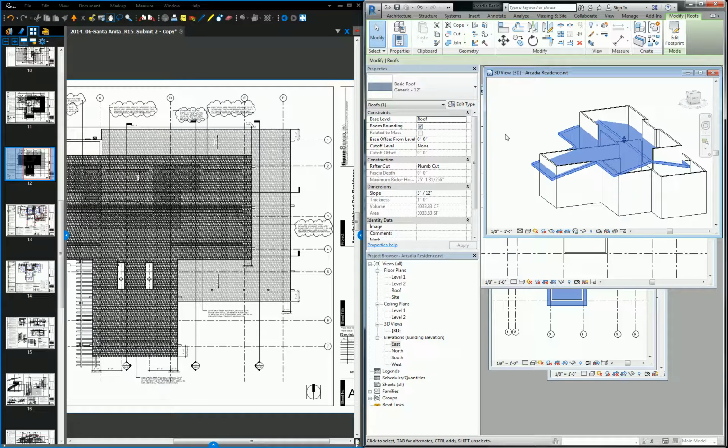The other thing that you guys will need to troubleshoot, and everybody should be paying attention to this one, is the top termination of each of the walls. As a default, I always hit no. I don't let it automatically connect walls to my ceilings or to my roofs and floors and stuff like that.